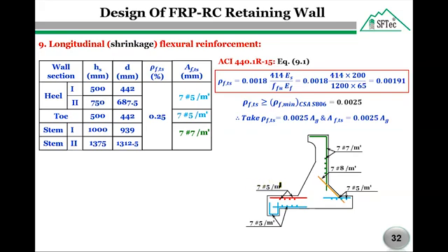For the compression steel in the transverse and longitudinal direction at the top of the toe section, 7 bars number 5 are selected in both directions. The selected bars in the transverse direction from the top and bottom will be connected as one piece.